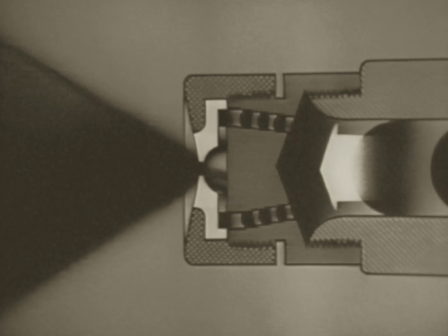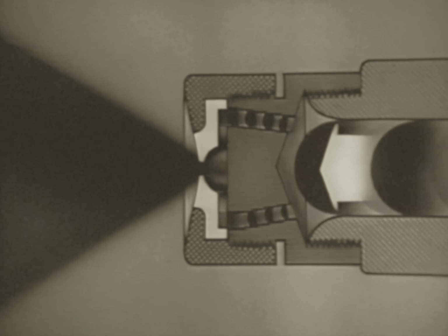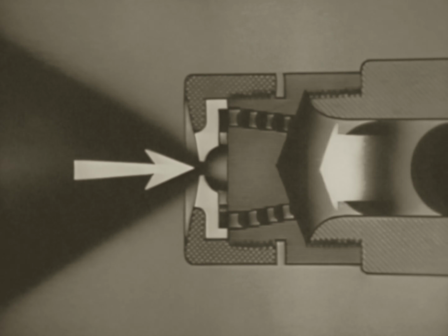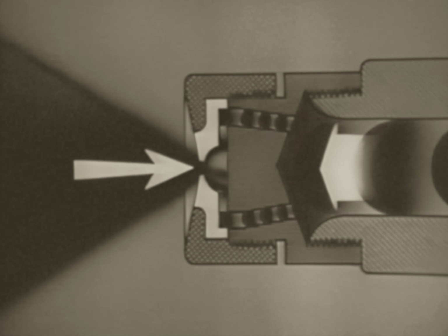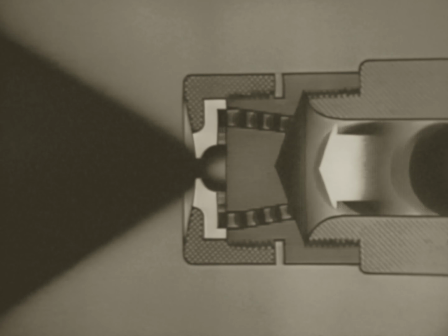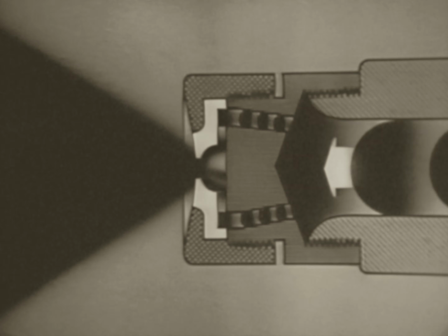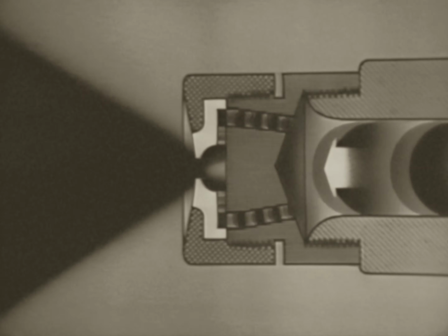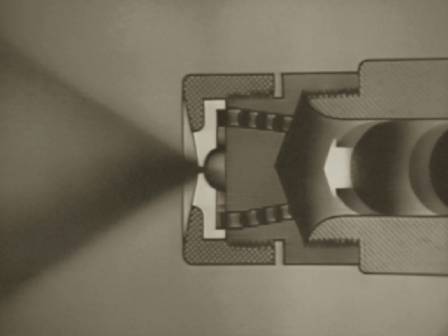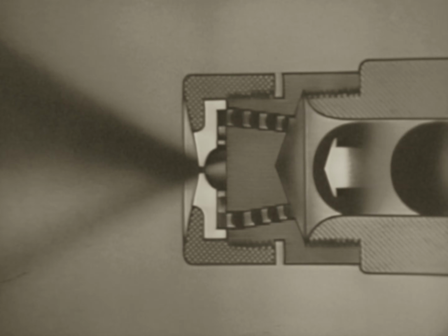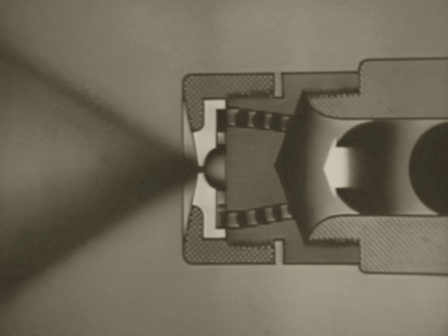However, when you want an increase in the firing rate, the sprayer plate in use at the time may have too small a capacity. That is, too small an opening to provide the necessary quantity of oil, even with oil pressure at maximum. You must substitute a plate with a larger capacity. When you want a decreased firing rate, the sprayer plate's capacity may be too large to properly atomize the reduced quantity of oil. You must substitute a plate with a smaller capacity. Frequent changes are necessary because the operating range of a given sprayer plate is very limited.